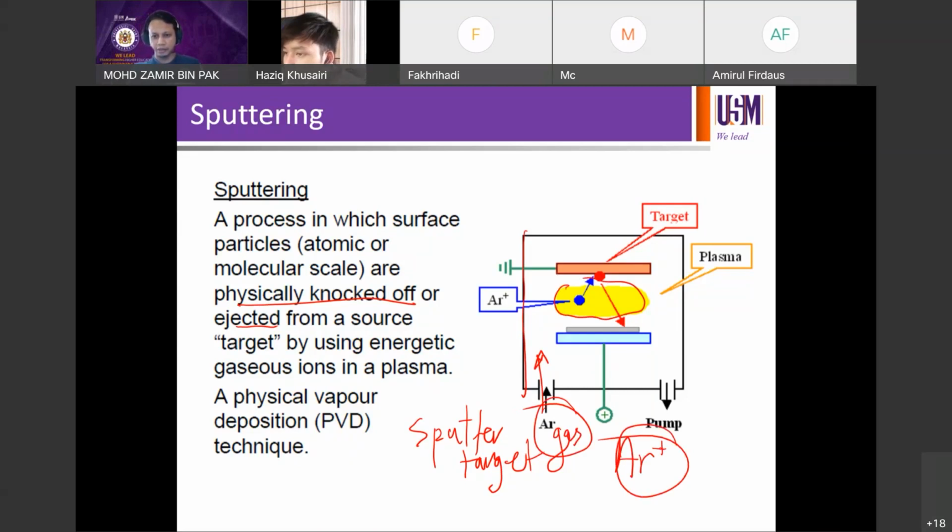And then the chamber and the pump are connected to the piping, the line here is connected to the pump in order to create the vacuum level. It's typically evacuated down to 10-5, and that is called the base pressure. So you can pump down to 10-5.